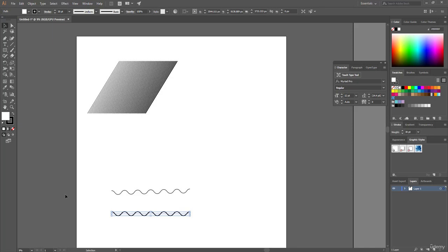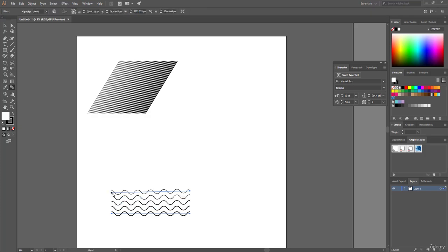Now from the left side I select the blend tool again and click on this point of this line, curve actually. Now I select these two curved lines and then select the blend tool and select the point of this curve and select this point.